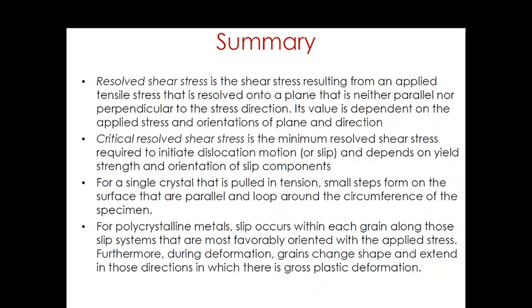Furthermore, during deformation, grains change shape and extend in those directions in which there is gross plastic deformation. So polycrystalline materials are stronger than single crystals because more obstacles are present in polycrystalline material for slip to occur.